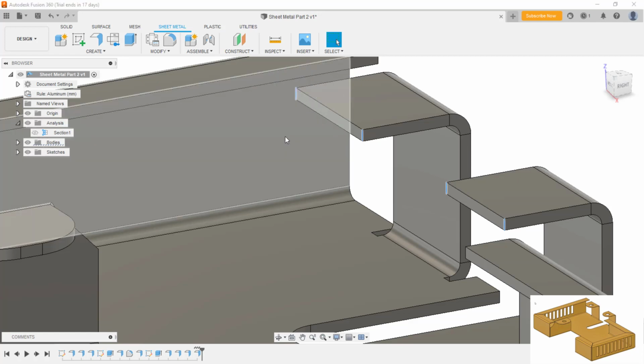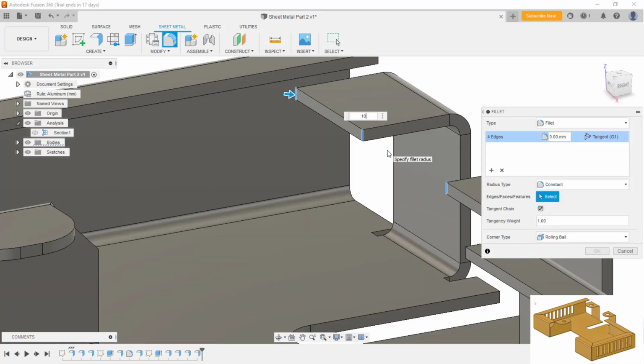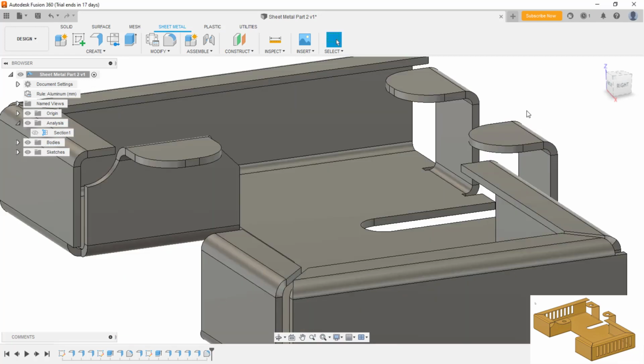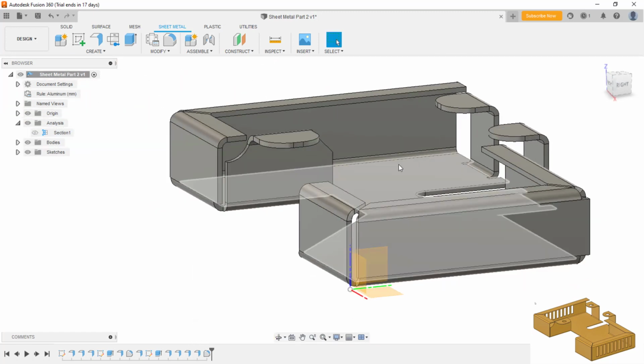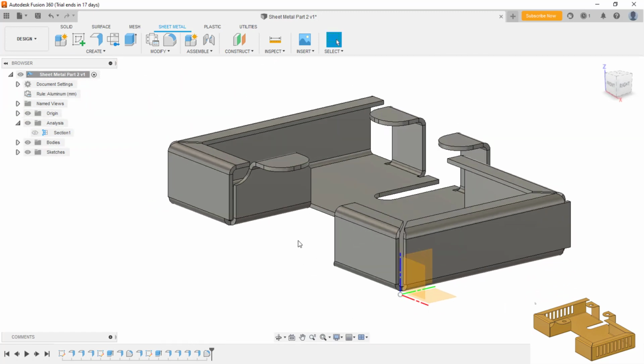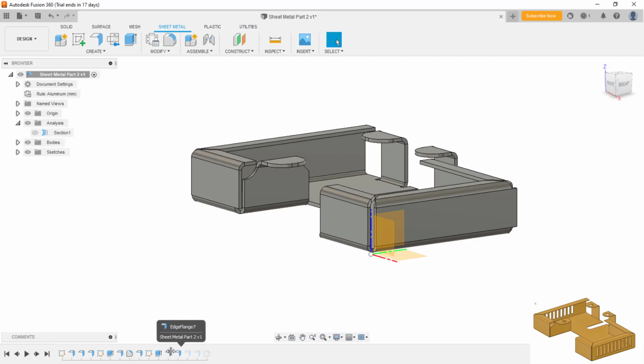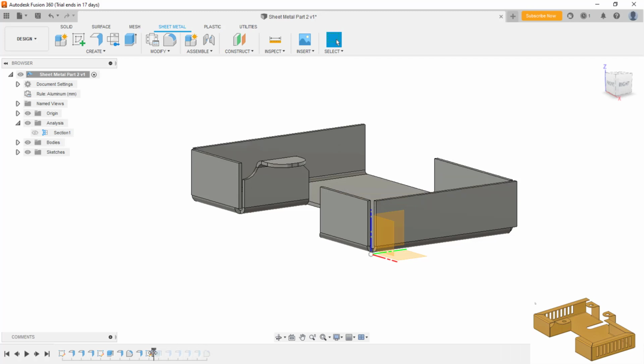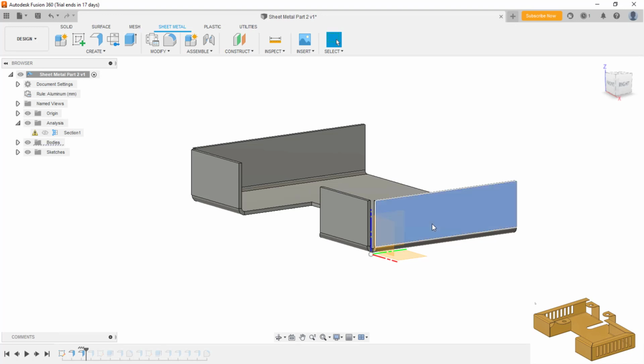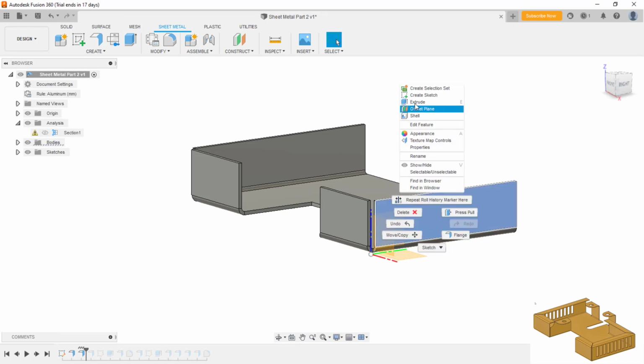Yeah, so right click and use the fillet. Here I'll assign it as 10. This is fine. Now as you could see at the corner, I need the cutout. So what I'll do is use this rollback bar up to a certain location. So these features you can roll back, and wherever you want you can create the features so that your entire design won't be disturbed. Now here I need the cutouts to be placed.